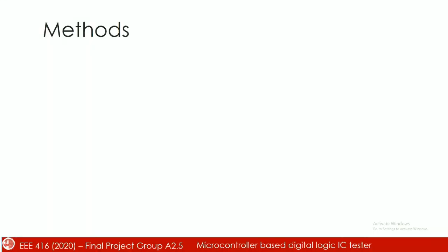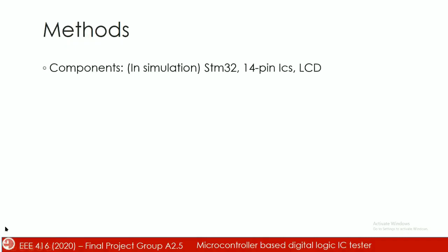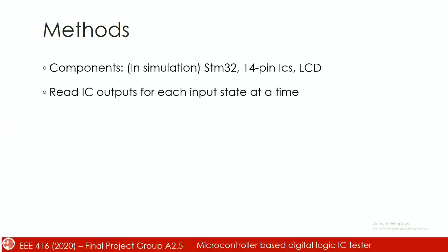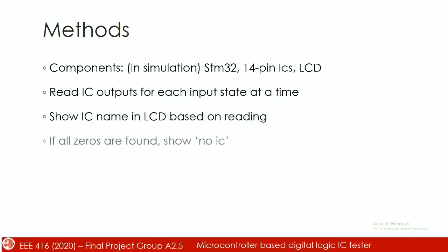Assalamu alaikum. My name is Mohammad Jain Alam and I'm going to be talking about the methods that we followed during our project. The components that we utilized are STM32, a 14-pin IC or ICs, and an LCD. During the simulation, we read the IC outputs during each state of the input provided by the STM, and the readings based off the outputs are evaluated by the STM32, and based on that, the LCD shows the IC name.